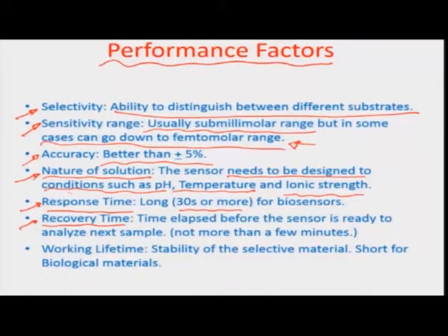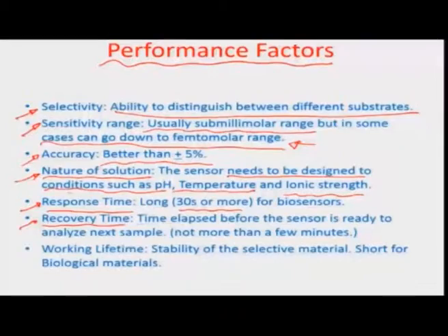to the baseline signal, so that it can start sensing another analyte or another solution or another sample, and for that you need to find out how much time is elapsed before, and what are the protocols that are to be carried out, if any, for a surface to again recondition itself, which again measurements can start taking place. So, time elapsed before the sensor is ready to analyze the next sample, that should not be typically more than a few minutes.